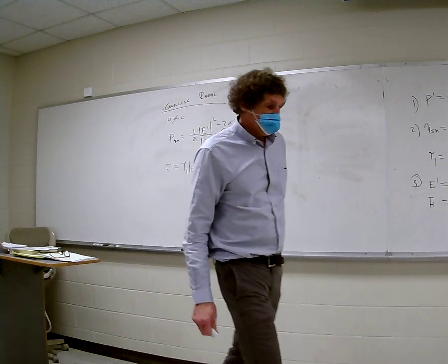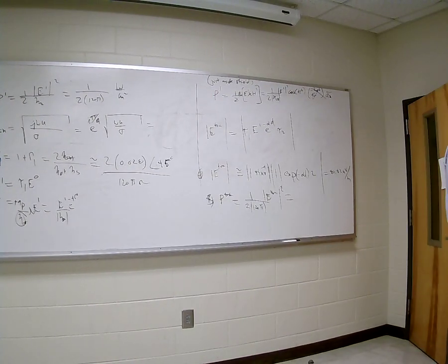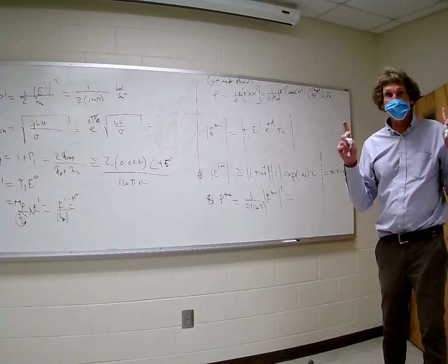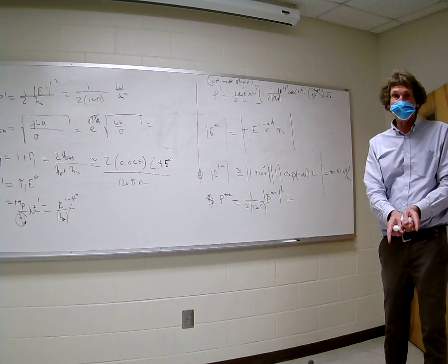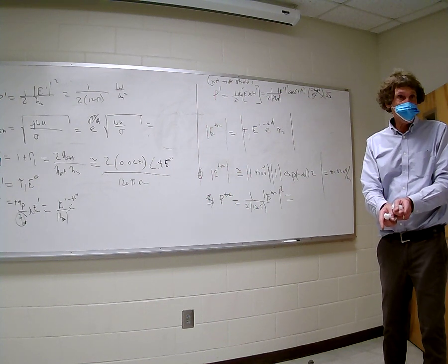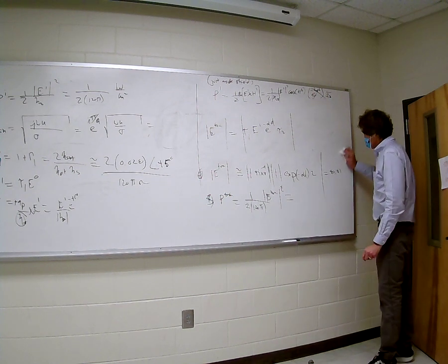Now, this one, I gave a whole lot of benefit of the doubt because I should have said what modes, not what mode, and the impedance of the mode. So if you had any mode correct and you had the right impedance, phase velocity, and stuff, you got full credit. But if you put like TM11 or something like that, then you didn't get much credit because it can't be a TM mode, and I'll get to that in a second.